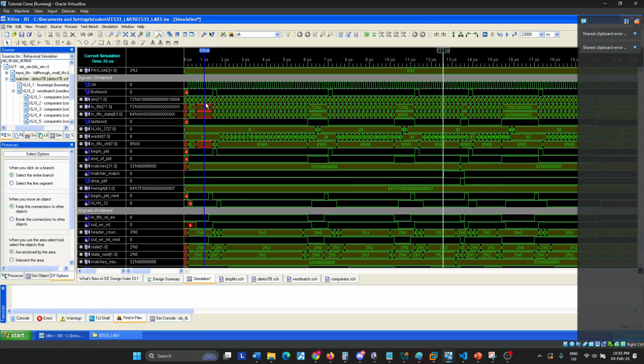So this data, which is 10004, is essentially 1, 2, and 3. So there is a 3 packet delay before the pattern matching actually starts to match our input data. Finally, we have the last word. This signal will be up when the packet has been completed and the FIFO sees the last word here.